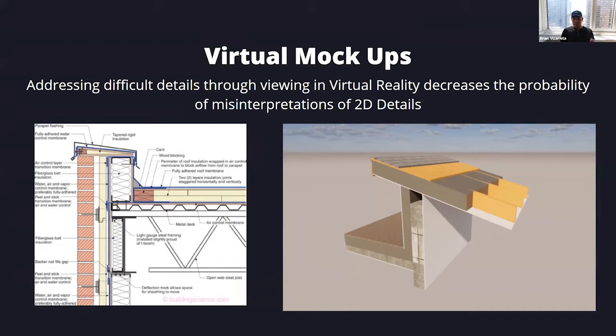In this particular scenario on the left, you'll see just a regular 2D architectural cut section, and you can begin to see how things start tying into each other. But that might only work well in that one specific siloed scenario. When you are able to drag a cut section across in 3D, you can say that parapet's actually at a slope, and once it intersects, you actually need a custom piece of cladding that you didn't think about.